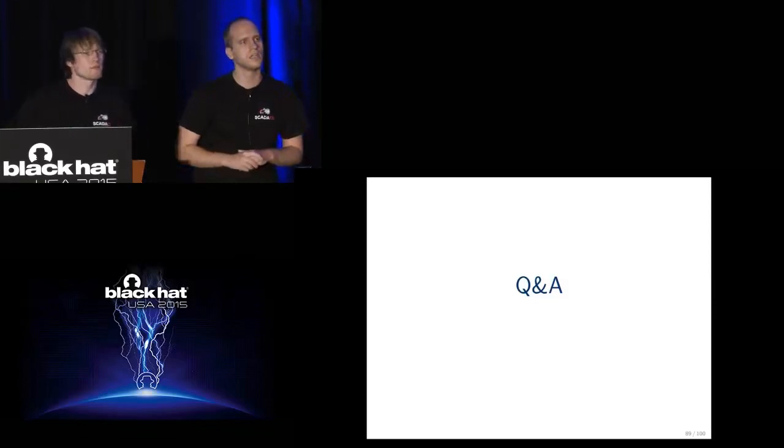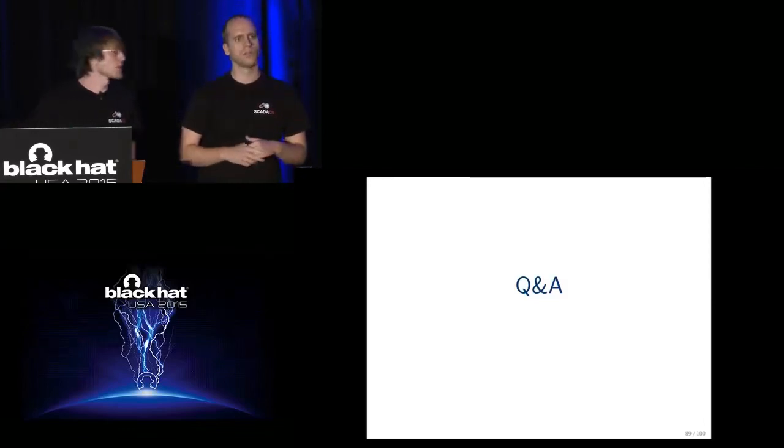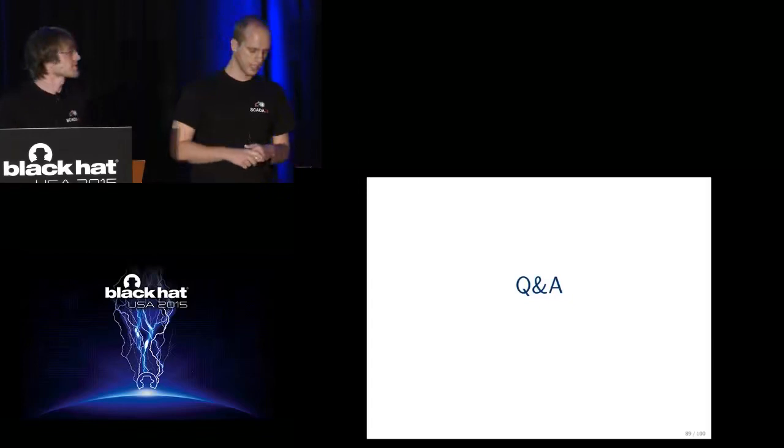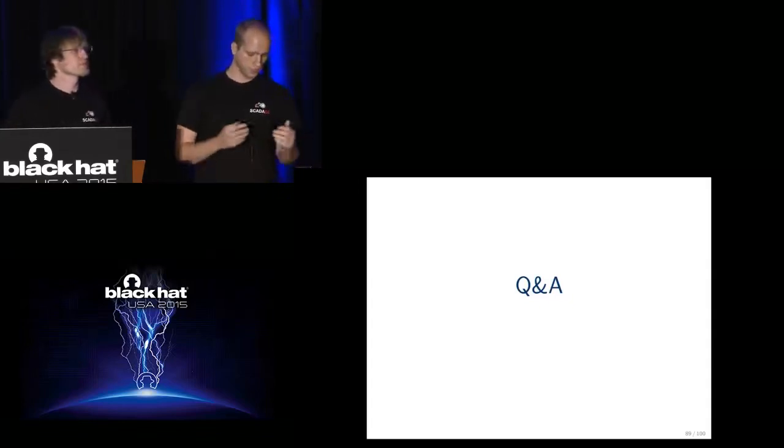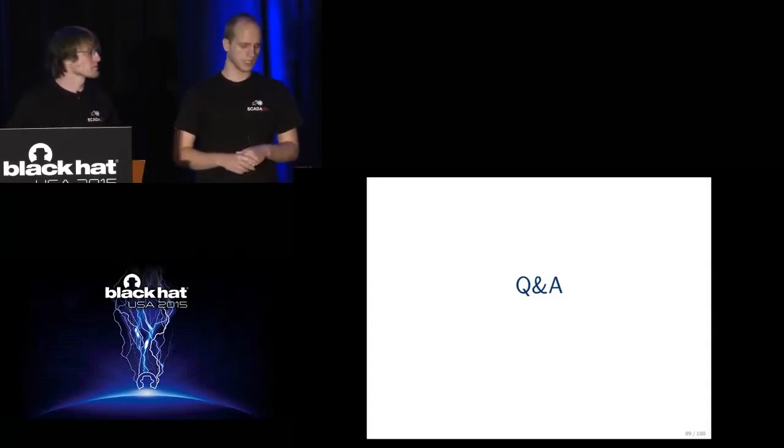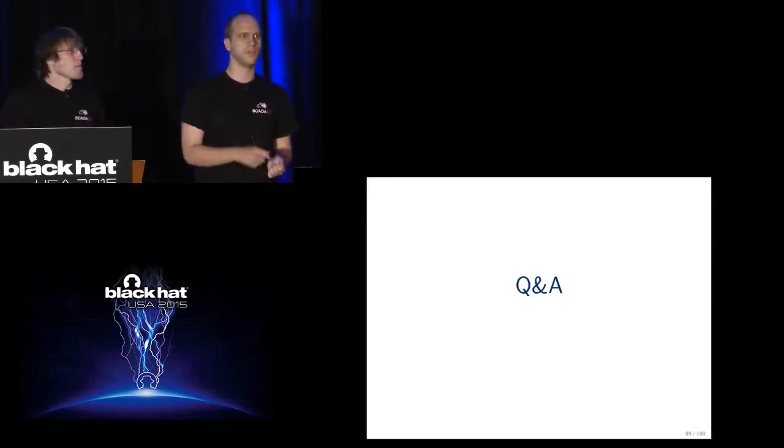Did you ever brick any of these devices, and how hard would it be to brick the PLCs? Brick them. Okay, yes. So we have not bricked one. We have just found the denial of service exploit. And if you run the denial of service exploit, you just have to go there and switch the PLC off and switch the PLC on. But you have to do it manually, and you have to be in front of the PLC. But we have not bricked one so far, so no.